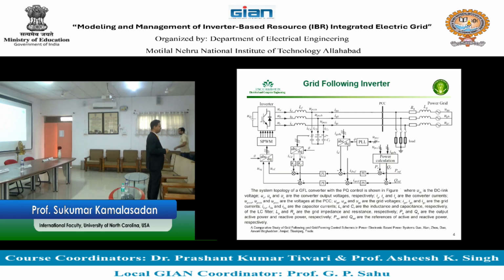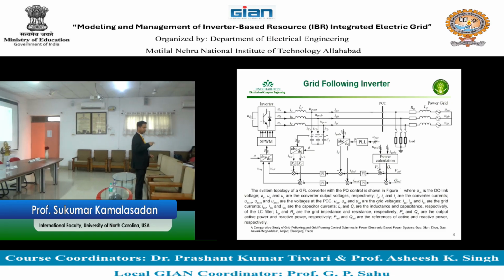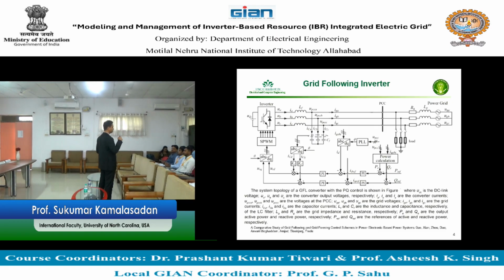When the power connected to the DC side of the inverter is changing, the voltage on the inverter's DC side changes. Now you already understood the relation between power and voltage, right? If you push the power, wherever you push the power, voltage goes high. If you absorb the power, wherever you take the power, the voltage goes low. So active power is directly related to voltage change at the terminal, right? And it changes when it pushes other places too.